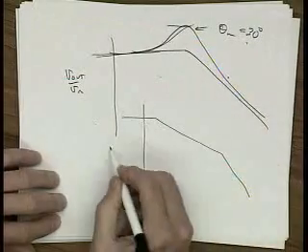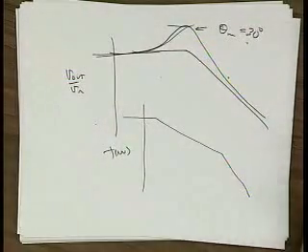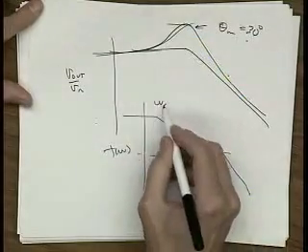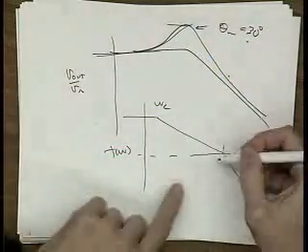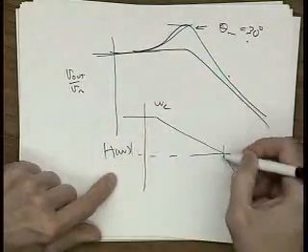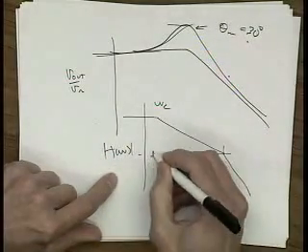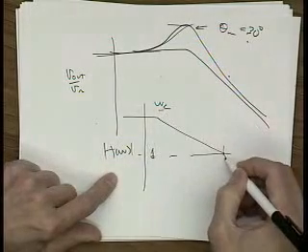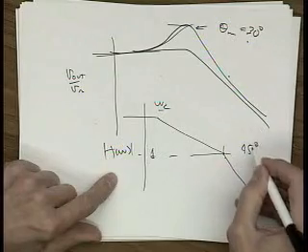When we do our T of omega test to figure out phase margin, right? Let's say here's the unity gain, here's our compensation pole, and we set this thing to have a certain frequency response, and here's our unity gain frequency, right? So we set omega compensation. For this case, let's say there's 2 poles, and this is a 45 degrees of phase margin case, okay?